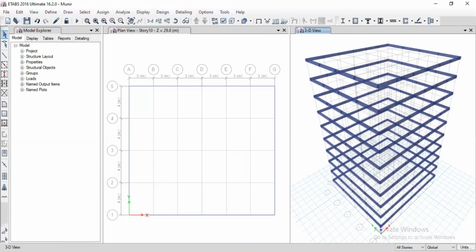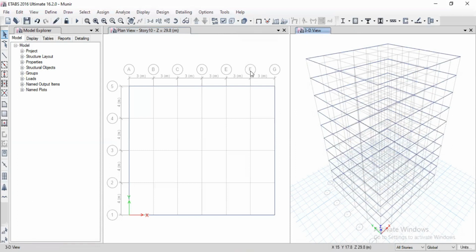Yes or no? Right? And when you click on that again, the 3D view disappears. For appearing and disappearing, all are done by using this click option. This is for both column and beam, for every member. Now next we have to assign the internal beam.